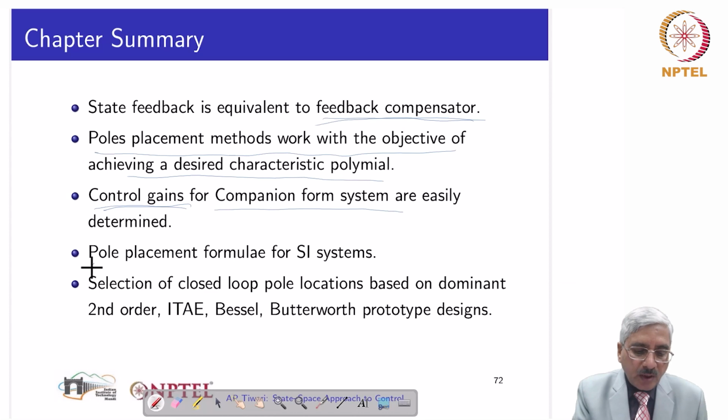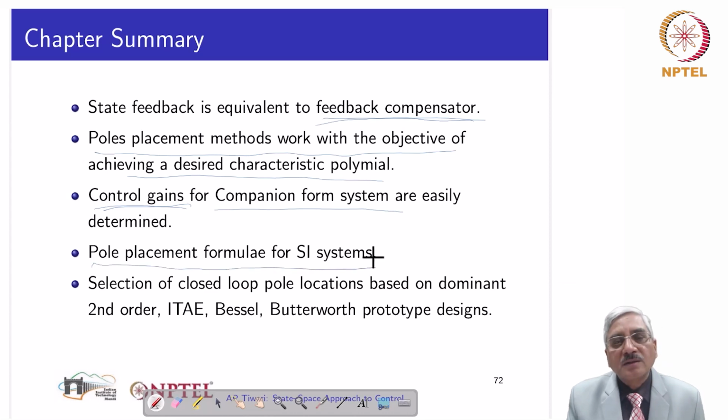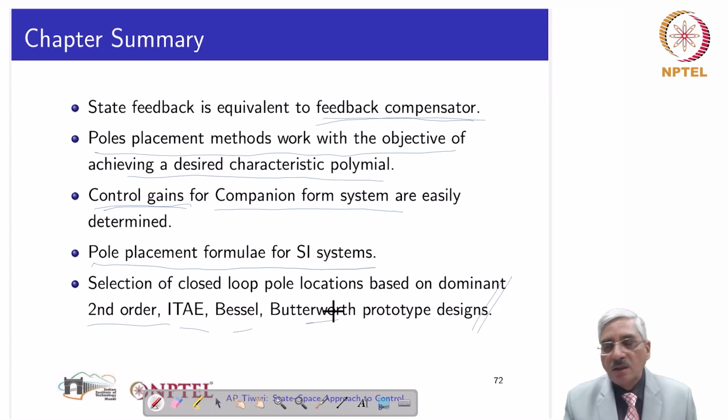We have pole placement formulae for single input systems. So when we have to design control gains for single input systems, we can use Ackermann's and Bass and Gura formula. And we have guiding prototype design based on second order dominant, ITAE, Bessel, Butterworth prototype designs. So we can use that.